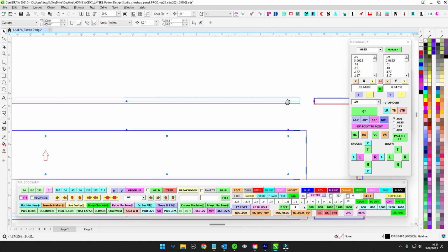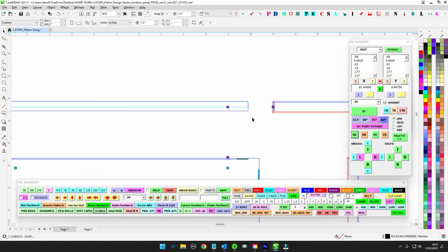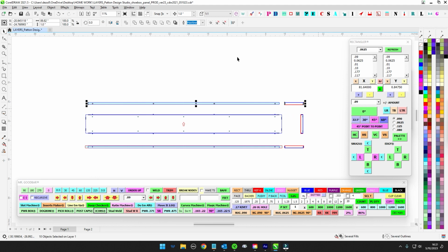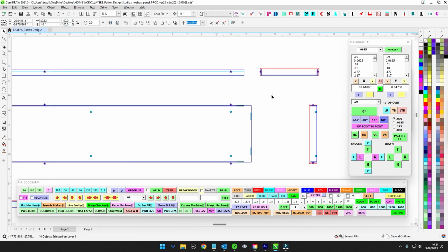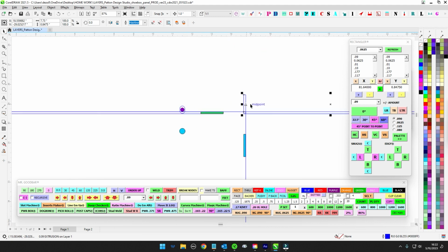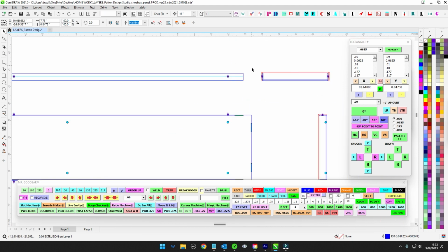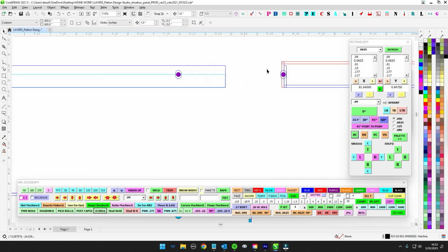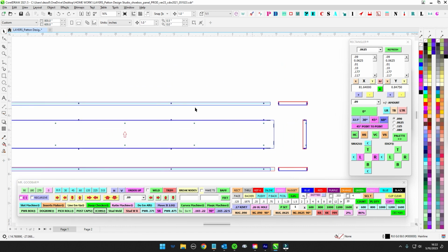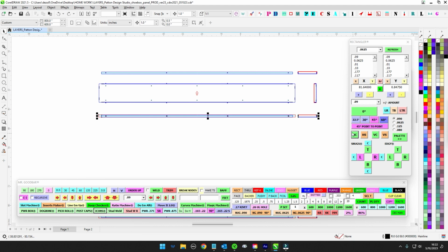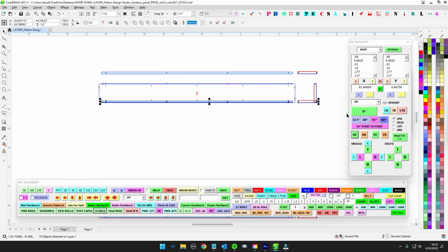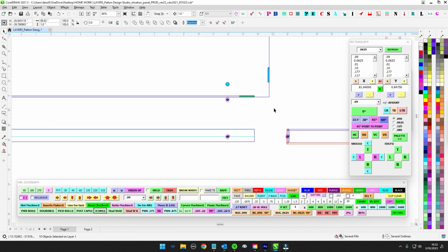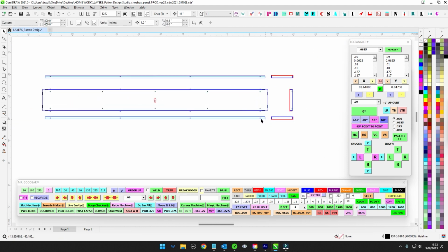So now we know that this backer is actually flipped the other way. So what we want to do is mirror this, so that this blue is lined up like that. That's the flange. See how the flange is going to stick up? So we want to make sure that this is the proper direction, right? The shorty side goes to the face. So this is properly aligned. And we can go ahead and get rid of that. And we can just duplicate this forward and flip it and smack it, make it good. So we're going to go there.